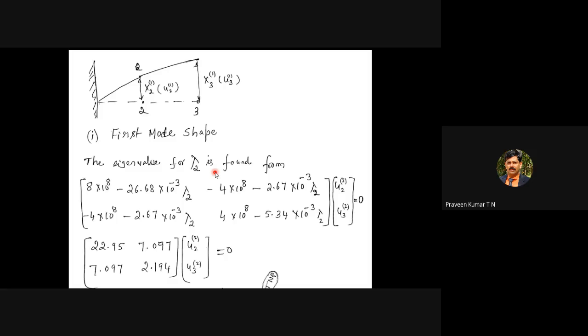So at lower frequency, the vibration pattern is different. Especially at lower frequency or lower speed, the vibration may be very high, especially in some cars. Even when you're starting buses, the vibration level may be very high. But once it reaches steady state, the vibration pattern only changes when the speed changes. If speed changes, the frequency of vibration also changes. We have the relationship between frequency and speed.